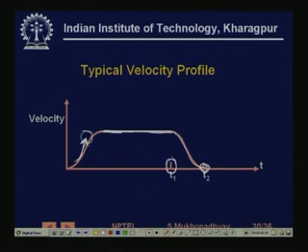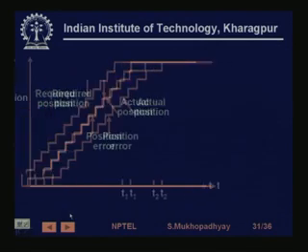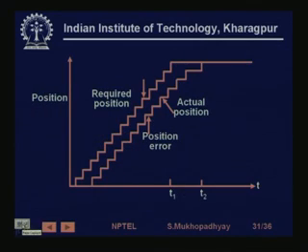So there is a natural deceleration in the process, along with the fact that you can also slow down the reference pulses using a deceleration circuit in the interpolator. So this is a typical velocity profile that may be followed. You can see that the position error changes like this: if you just integrate the velocity profile you will get this position error.